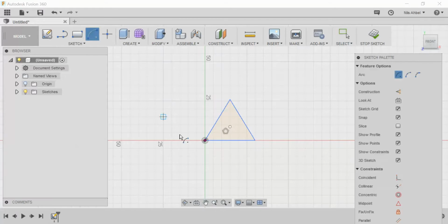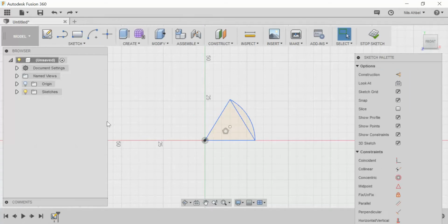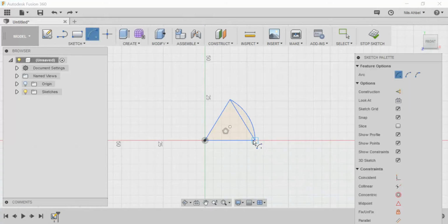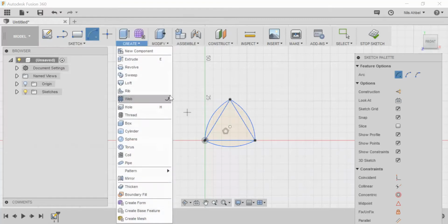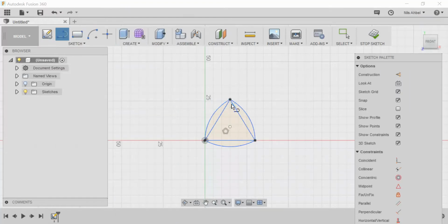I can zoom in here a little bit. I can use this center point arc tool to create all 3 arcs. Oh, you see there I didn't snap, so I can do undo. It's important. It won't work. Print out nicely. There's what I got to do. And there. I'm going to create a line. L is a shortcut, so I can just press L and it'll bring up the line tool. And I'm going to put a line down the center here, from here down to here.